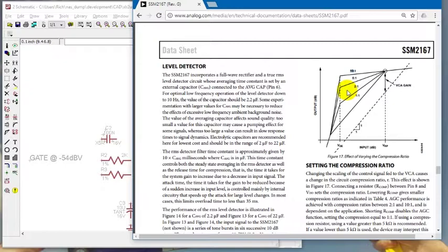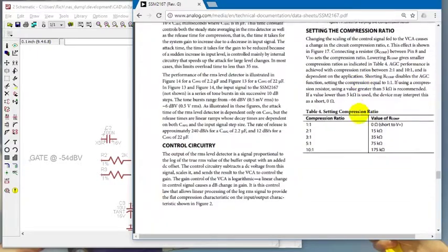And then as it stops being that loud, you come back up. So if you were watching the little VU meters on your tape deck, if you're an old hi-fi system, you say, okay, I'm going to set it up at 0 dB, let it come through, and then as the needle pegs up into the red, then you bring it back down again. And as it gets out of the red, come back up. So that's what this ratio is: basically how aggressive you are. As it gets above the threshold, how much do you bring down the volume by? And 3 to 1 is not bad.